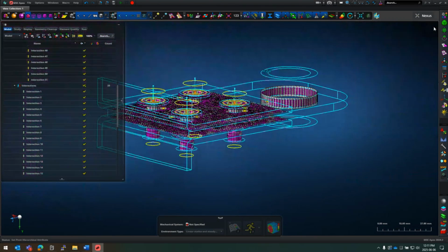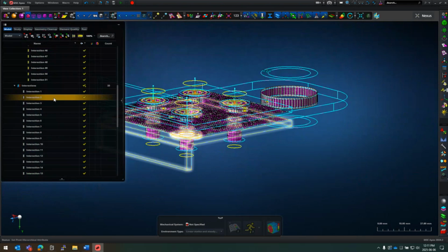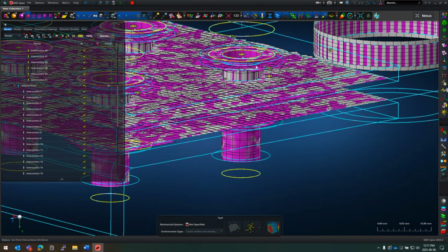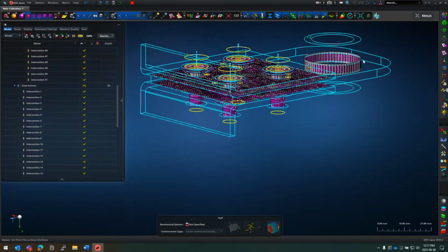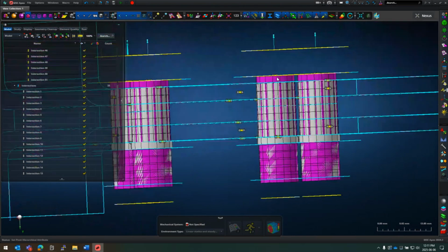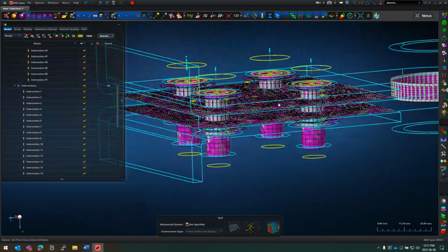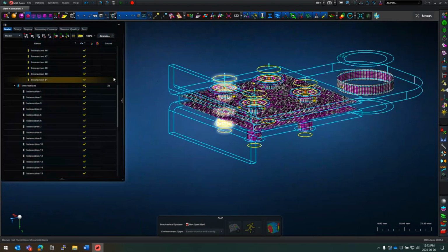Now let's say I need to change this, because by default on that auto creation tool, I set it to just glue everything together. But I want this washer to be able to slide. So in other words, if my load is big enough, that bolt should slide and then probably make contact there. And I'm not going to set the contact between the bolt and the plates, but in theory, that's the correct way to have done this.